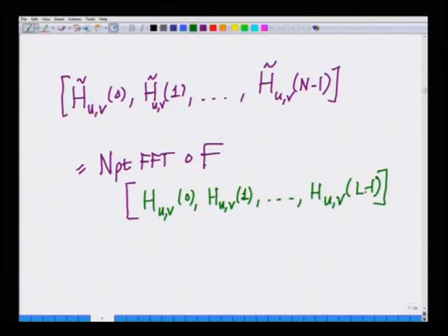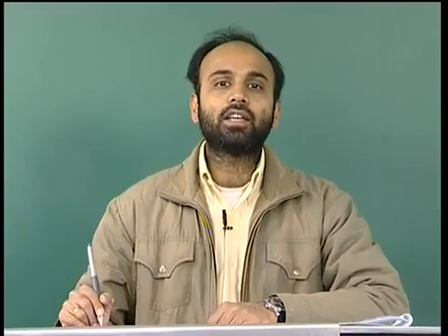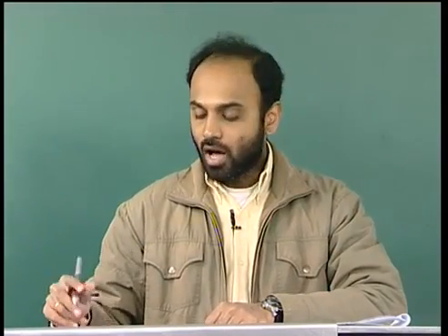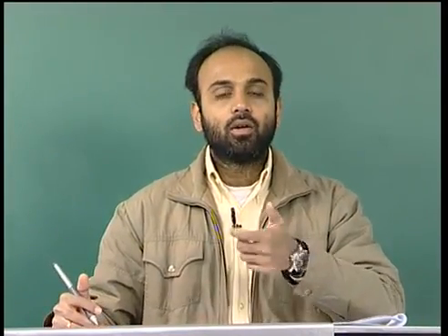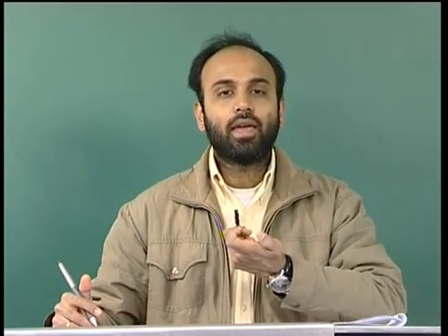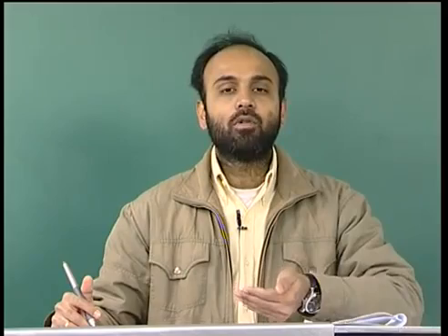Of course, this has to be taken after 0 padding. Since the number of subcarriers n is much larger than L, this n point FFT has to be computed after 0 padding. So, I take the uvth elements of all these MIMO FIR channel taps.